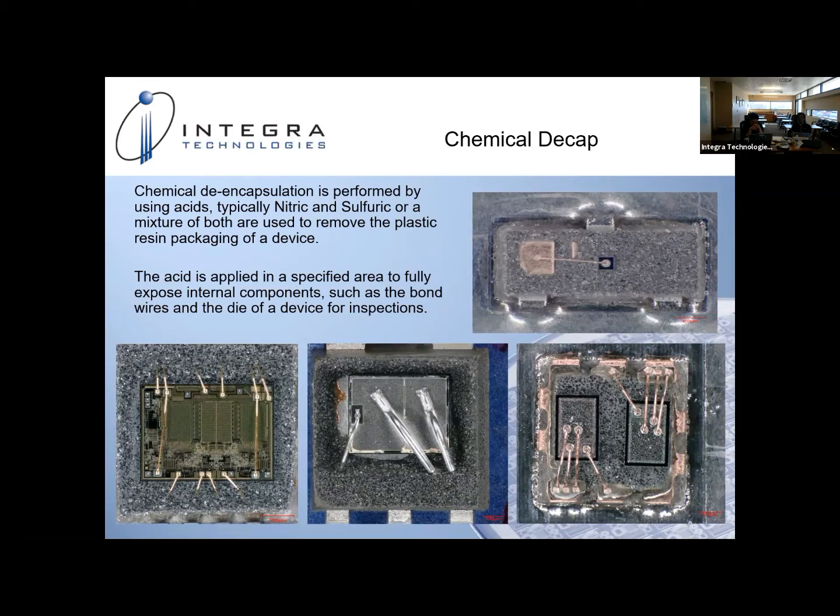You ablate it to maybe an 80% level, take the part, do some more acid etching, look at it, see has it gotten to the wire or not. Do a little bit more acid etching for another 15 seconds. So the process to decap a device could take as long as 4 to 5 minutes per device, depending upon what you are trying to do with the process.